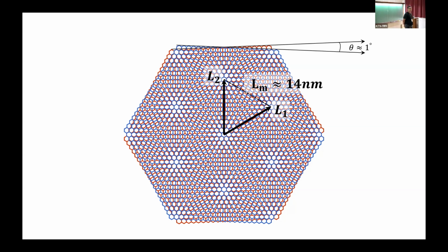And if that's the case, we can then use a field effect transistor to take the electrons in and out of these narrow bands and fill them, because the electric fields necessary to do that are accessible before a breakdown of any dielectric that you would need in this setup. Okay? And so that we can now do reversibly, unlike in many materials where, in order to change the concentration of the electrons, you have to change the chemistry, you have to introduce some dopants or something like this. Here we have the advantage of being able to reversibly add or subtract electrons.